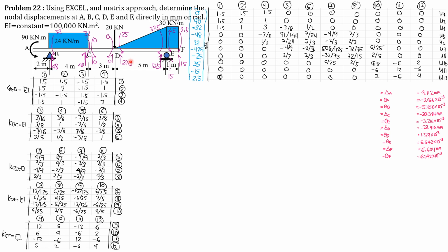So computing for FDE, you will get 22.5 kilonewton. So it's also not shown here, but in your scratch paper, you sum up moments about E. So fixed end force DE times 5 plus 37.5 equals 25 plus 1/2 of 5 times 30 times 5/3. So you get 22.5. Summation of forces y equals 0. So this is 52.5, though not necessary because this is support.